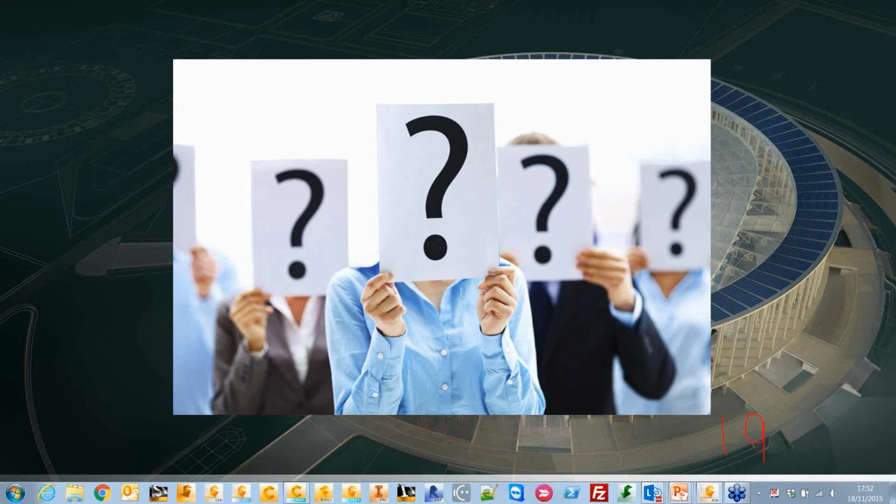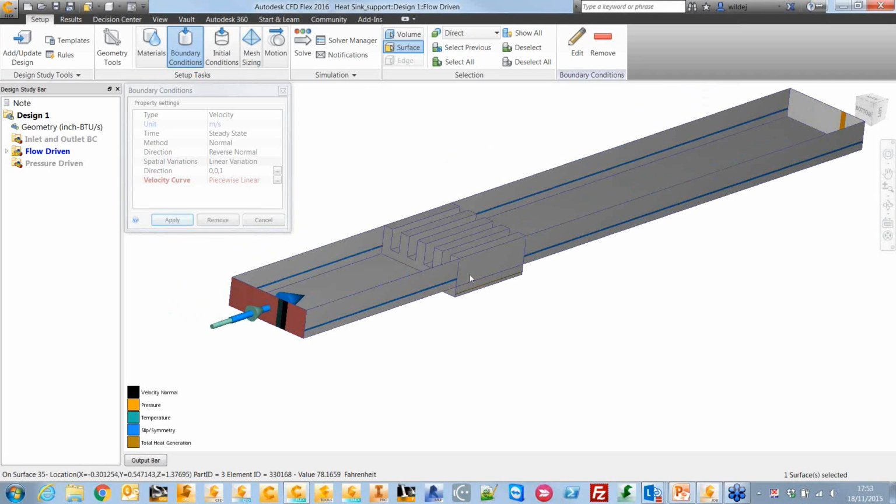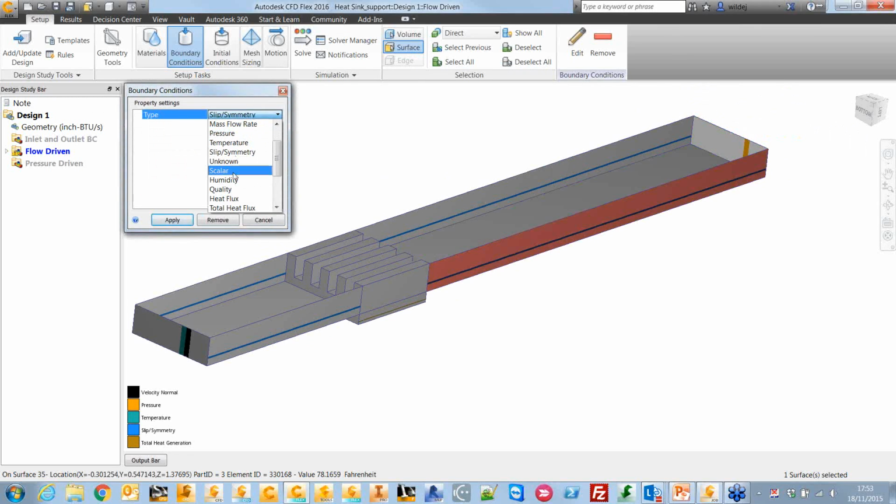There's a question asking about checks with film coefficient values. I'm guessing as to what exactly the question meant, so feel free to change it if there's something else you wanted to share. But we could assign film coefficients. Say if I assigned one on my sidewall here, so some heat was allowed to escape during my analysis. There's a couple of values that we tend to use really frequently. Say this is sitting in an ambient environment of 20 degrees C, that's going to be my reference temperature.